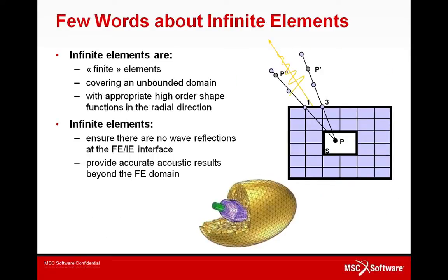So a few words about the infinite elements. The infinite elements are the natural extension of acoustic finite elements to model the far field radiation. You cannot see these infinite elements, you can only see their footprint on the finite element domain. But these infinite elements are actually finite elements in the sense that they have higher order shape functions that are used in the radial direction.